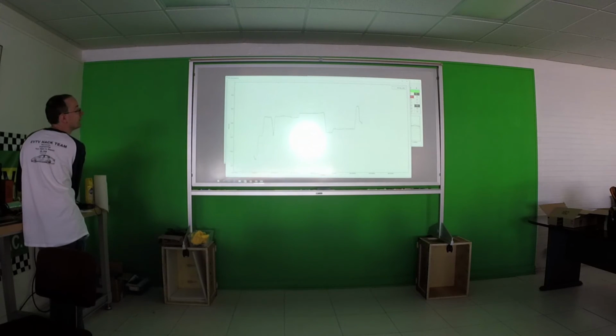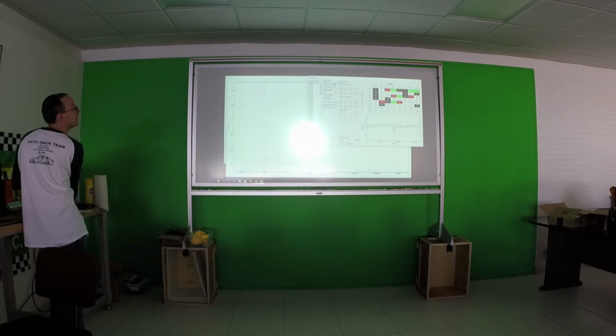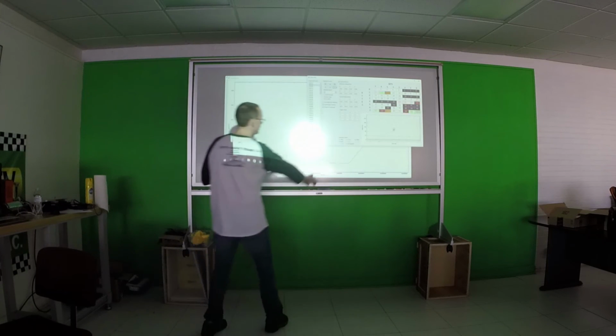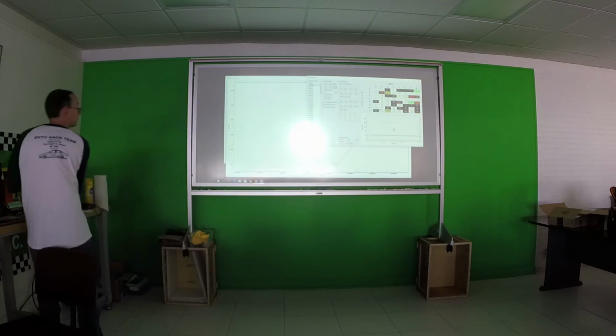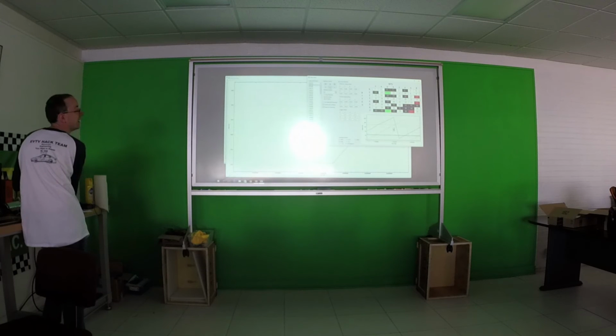And here we have the RPM graphed pretty cleanly. Now one thing you can do on this, let's say I want to zoom in here. We're looking at some data here, and I'd like to have the graph update while I'm looking at this so that the windows are synchronized. You can say synchronize windows here, click, and now the graph physically moves. So the graph is centered on the data that you're currently looking at. So that can kind of help to correlate.